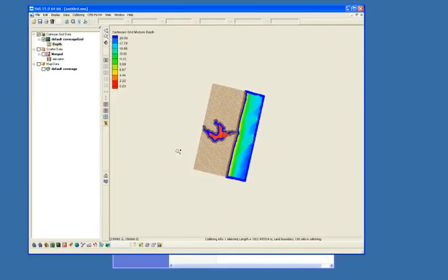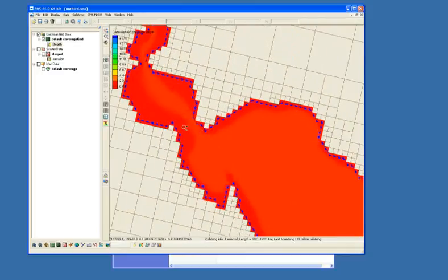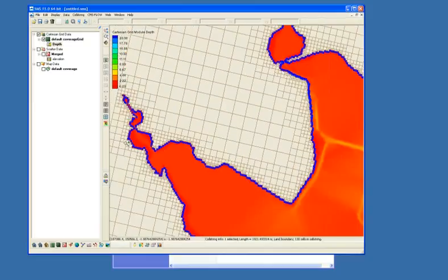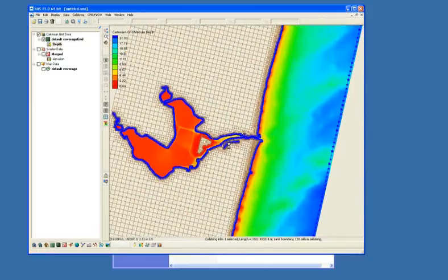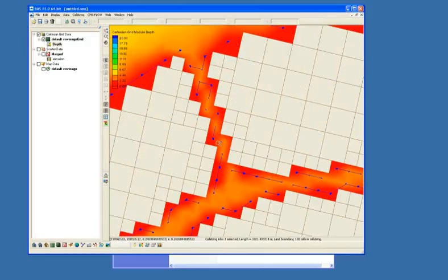Same thing on the other side. You can increase the resolution in some areas so that we get all the flow that we need. Down in this area, it's only 1 cell wide in a couple of areas. There will be no flow between these whatsoever. And so we need to make sure that we better represent that.